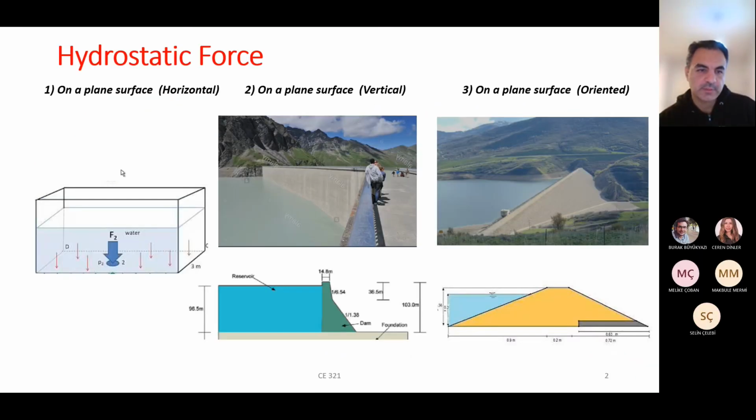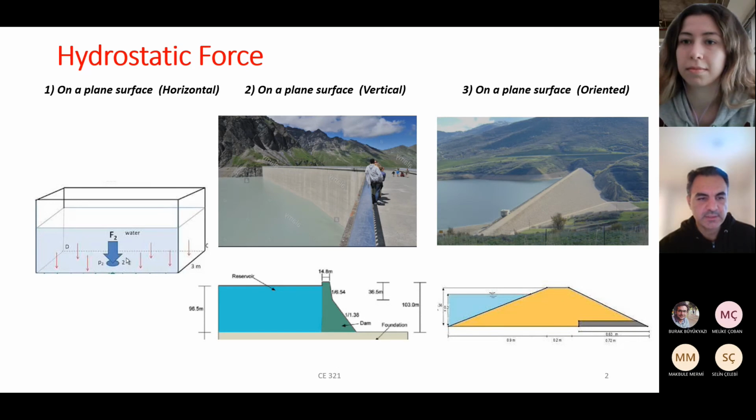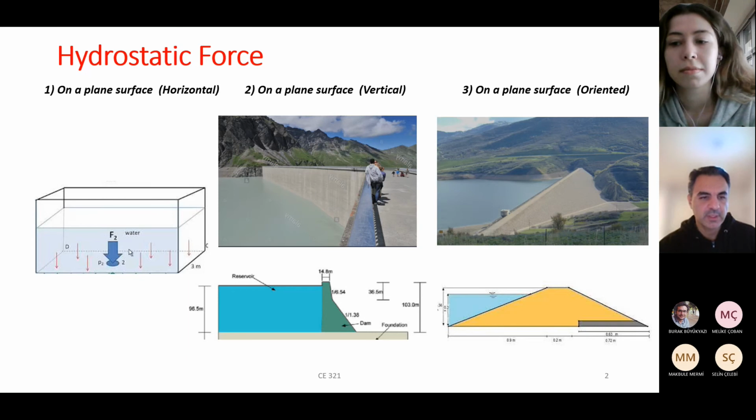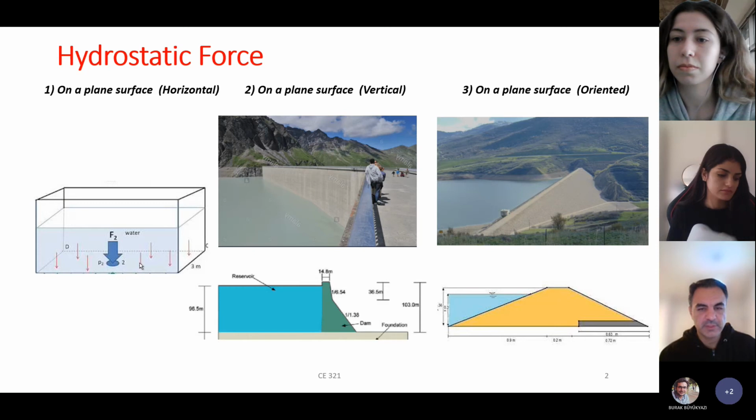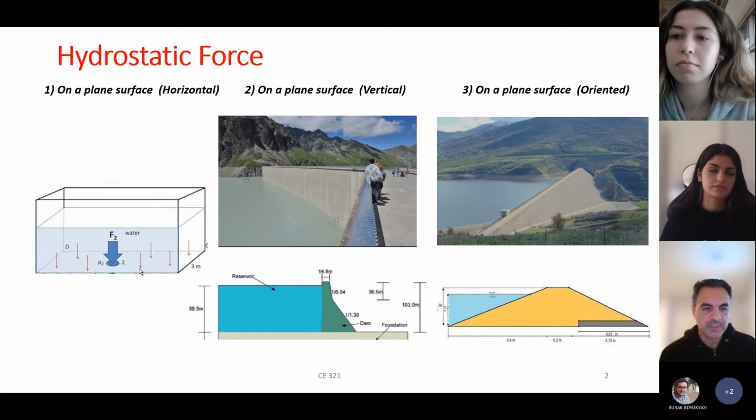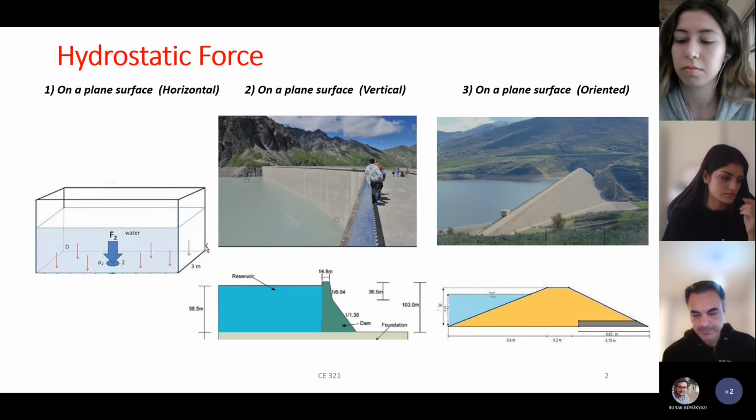so far, I talked about calculation of resultant force at the bottom of a horizontal plane. The easiest form, you saw that at any point on a horizontal plane, pressure is constant. Therefore, the value of one of those pressures should be multiplied by the area of the plane to attain the resultant force.